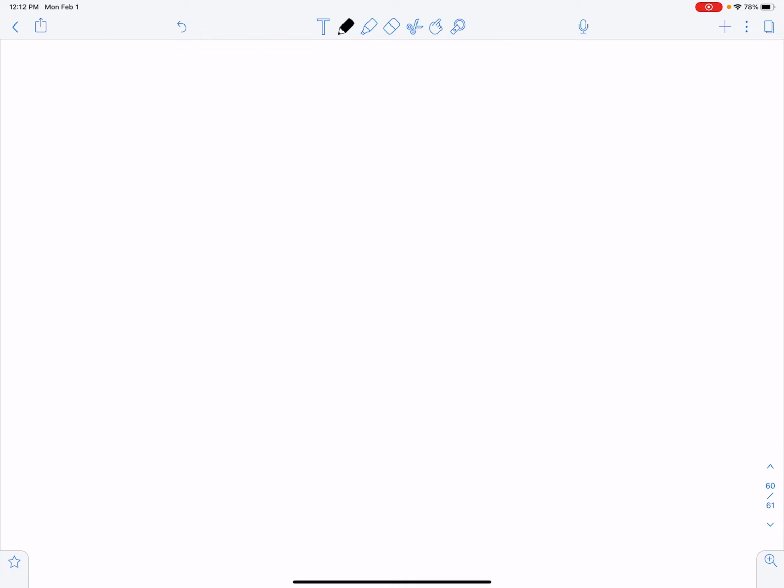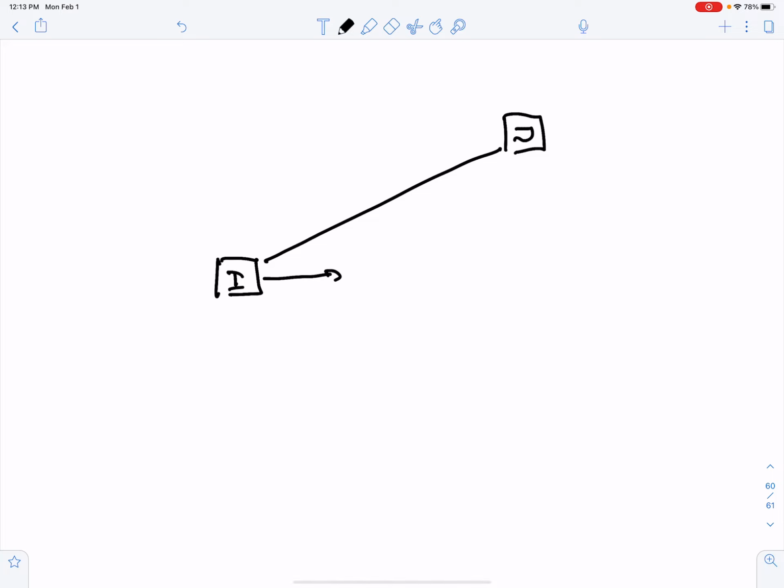So now, with these considerations, let's take our bar situated somewhere in space. This would be node i, this would be node j, leftmost and rightmost. Node i can displace in the global x direction, and I denote that displacement as delta 1.